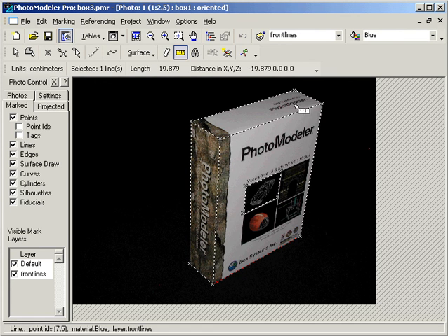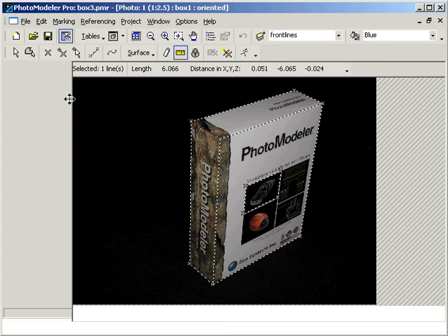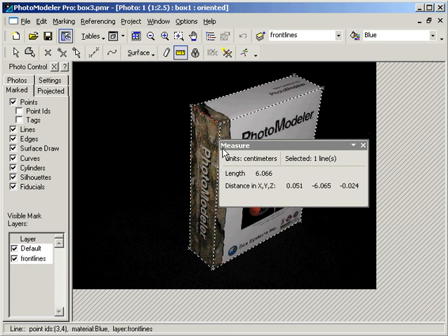Normally the Measure toolbar will appear up here in the main toolbar area. We are also able to move the toolbar to a floating location. For example, we want to measure an item in the photo and have the results displayed near the selected object. We do this by moving the cursor over to the edge of the toolbar, then clicking, and dragging it over to the region where we are doing measurements. The results are displayed in the floating toolbar.